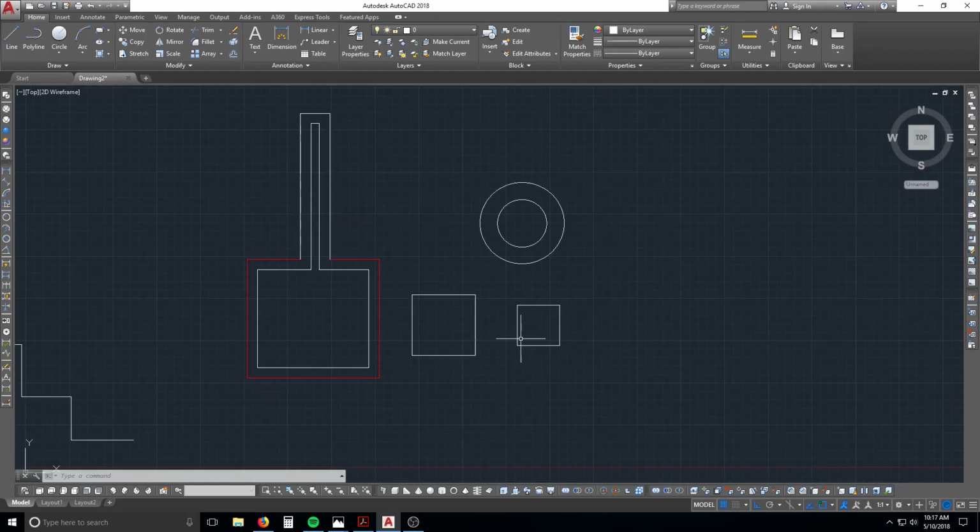And you can do that with a line that has 100 different sides, and as long as you pick all the correct points, vertexes, you can get very accurate, to thousandths of a square foot, or however you have your precision set up, exact square footage or area of whatever you're trying to calculate, whether it be for a roof or a slab or whatever. And if you get into doing 3D stuff, there's another command for that as well. But alright, so that was area.